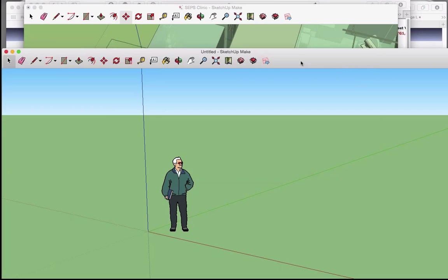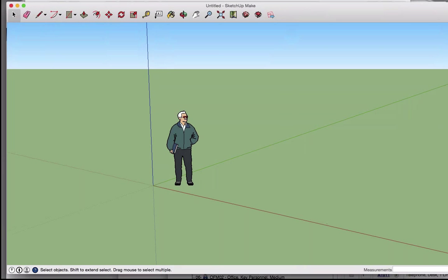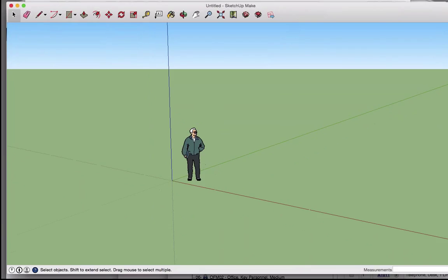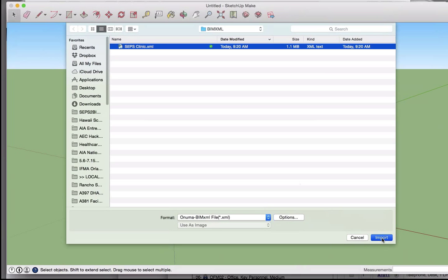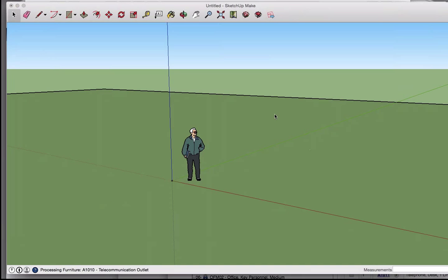And then one thing that maybe I have to end with is in SketchUp, the file that I showed earlier that was on the web, if we go and say, okay, we want to import it in, what happens, instead of going to the 3D warehouse and manually downloading each of the objects that go into the exam room, the import to SketchUp actually starts building it on the fly and grabbing. See how it's listing down here? It's actually going to the 3D warehouse, grabbing the actual object. Sorry, it's off screen at the moment, but it'll come into screen in a second. But basically, it places them in the room from the 3D warehouse.